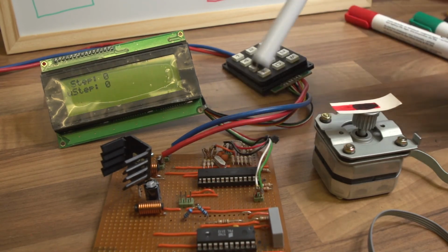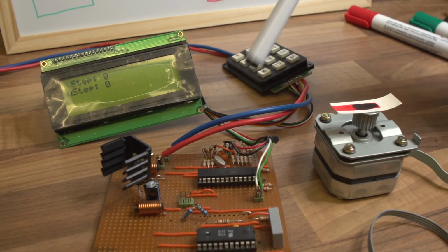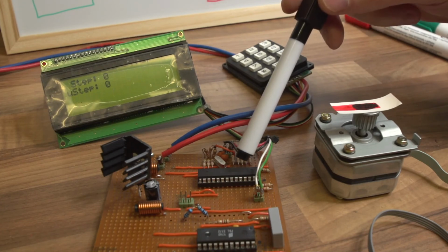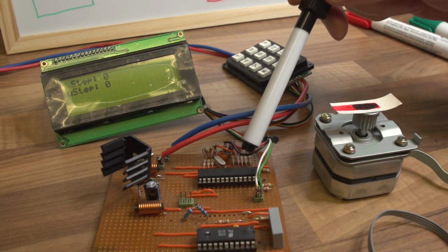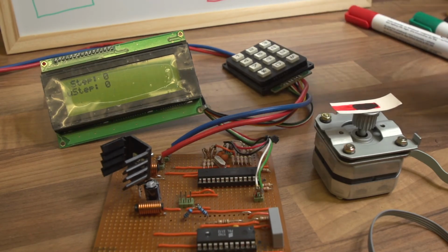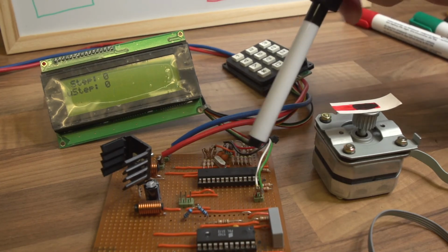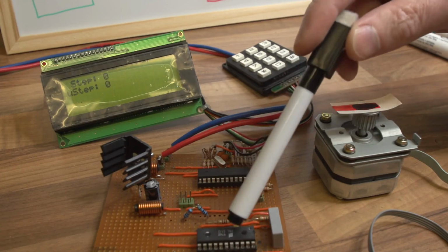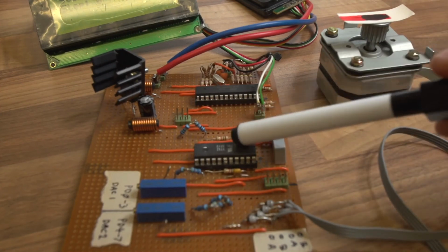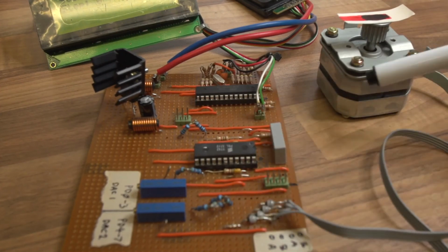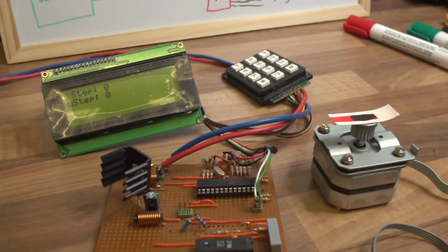It's all clever stuff. And when you consider this chip probably only cost about £1, it's pretty good. You've got your RAM, you've got your ROM. There's a program counter in there, which is all internal. You don't even need access to the address bus anymore because it's inside. But crucially, all of the I/O pins are available. Lots of I/O pins, and it's the I/O pins, the in-out pins, that we're using to drive the motor controller chip here, which then produces a phased output to drive the stepper motor here. So that's a practical example of something that you can build yourself.